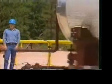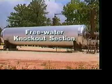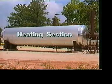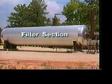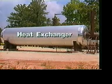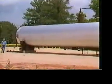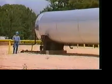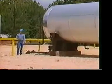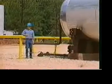The design of a horizontal heater treater may include the following components or sections: an oil and gas separator, free water knockout section, heating section, water wash, filter section, stabilizing section, and heat exchanger. Any number of modifications can be made to the basic design. For example, both the size of the internal sections and the amount of heat required may vary. Another example could be the need for a filter or hay section.